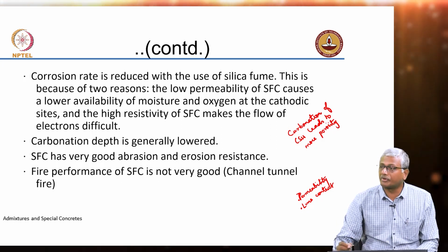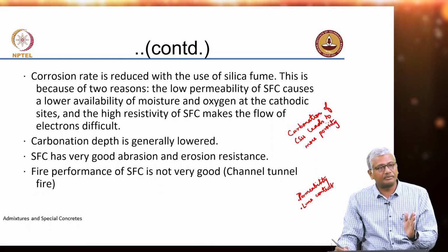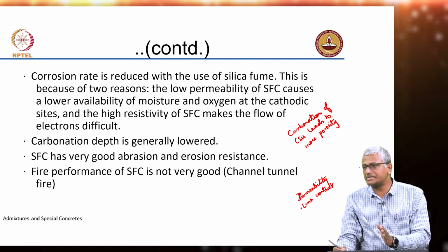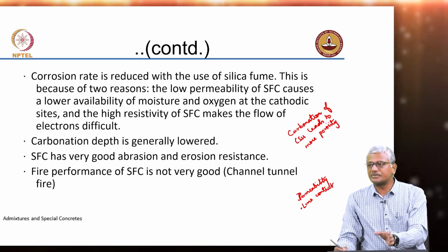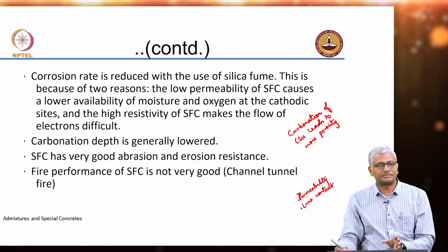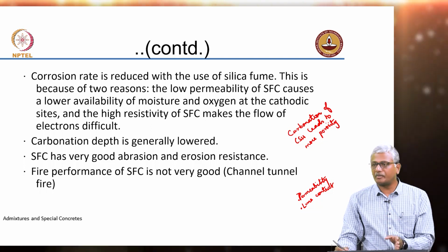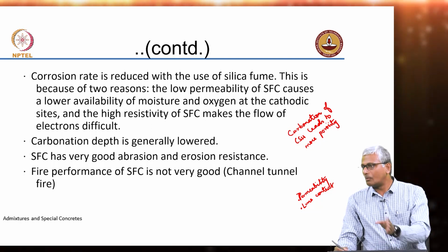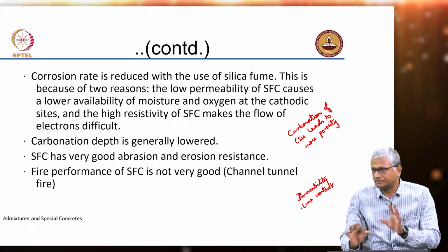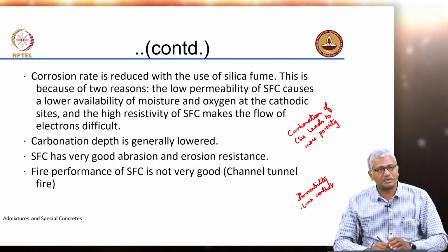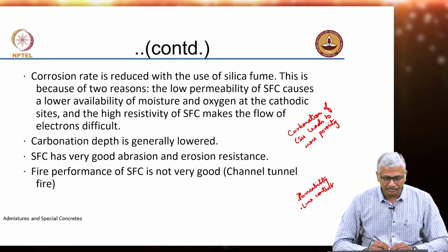So, if it leads to more porosity, obviously more CO2 also will go in. So, your penetration depth in concrete with blended cements is generally going to be more than the penetration depth with OPC. But in the case of silica fume concrete, there may be an exception. Okay. You may have sufficiently low permeability with silica fume concrete to avoid the effects of reduction of calcium hydroxide content. Well, it depends on a case by case basis, but on the whole silica fume concrete may show a lower carbonation depth.